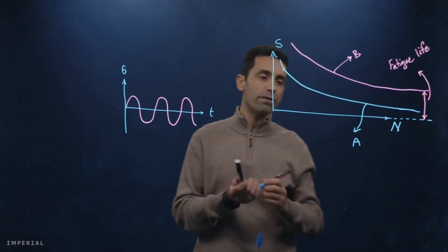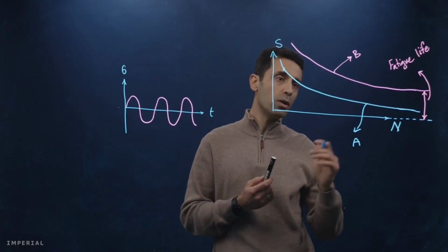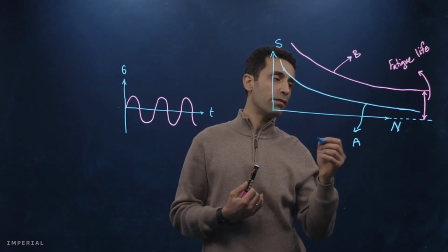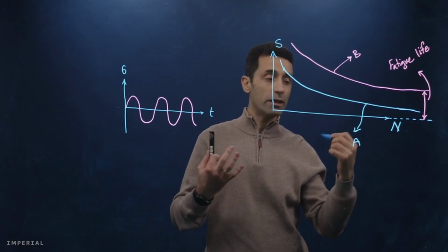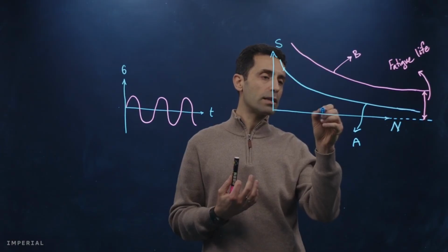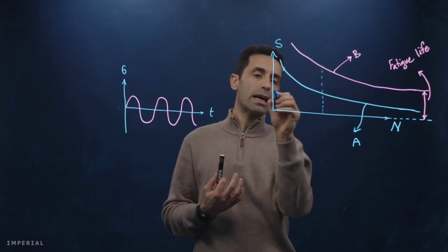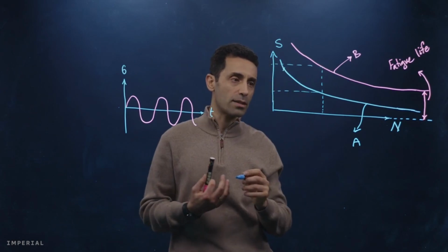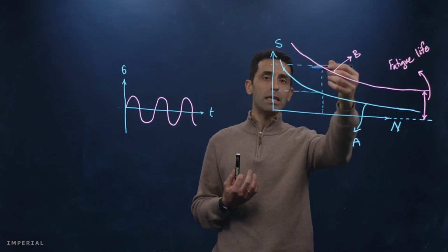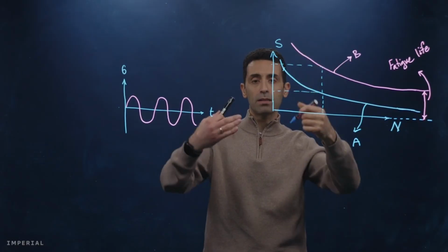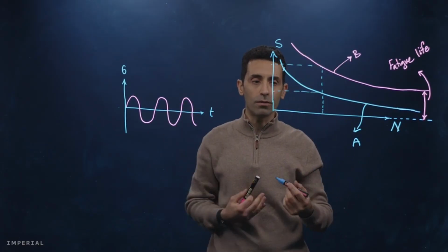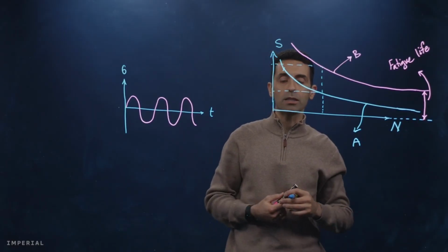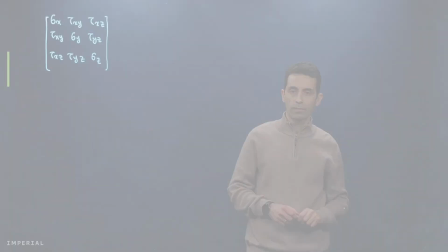So if I then want to know at what level of stress these structures will fail for a given number of cycles, so if I get these cycles, then I can go on the y-axis and determine the magnitude of S. And as I mentioned, B has higher resistance because it will fail at a larger value of this alternating stress when we are applying the cyclic loading.